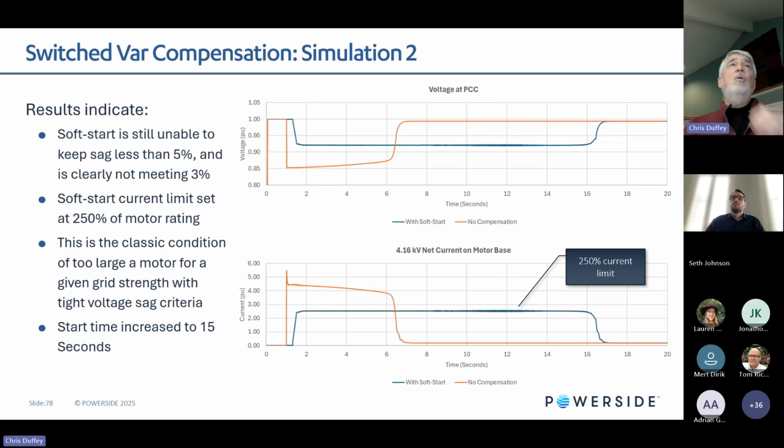So this is an actual start, the soft start itself, and this matched an actual benchmark that we were supplied in terms of a measurement. So we are getting to, again, about a 7% voltage drop, and that was an unacceptable condition from the grid PCC side.